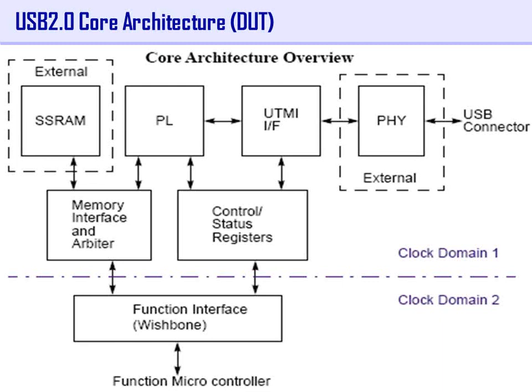You know how many interfaces it has got? What does each interface have? Interface is only of two types, whether master interface or slave. If it is master, you need to connect what? Sequencer, driver, monitor. If it is a slave interface, the only thing you need to connect is what? Monitor and slave model. It's either a memory model or a slave model. You know all the inputs. No? Can you draw the testbench chart?